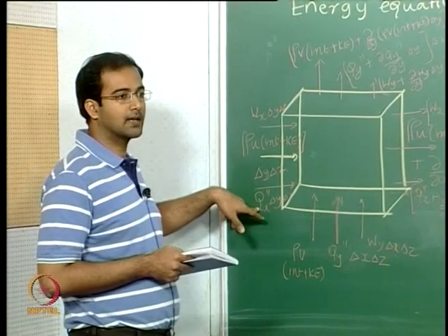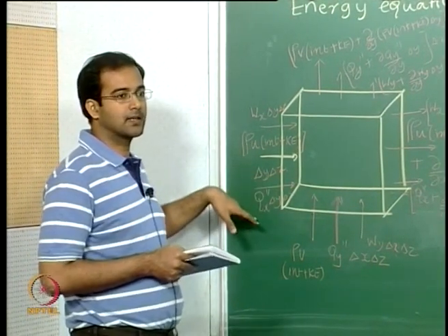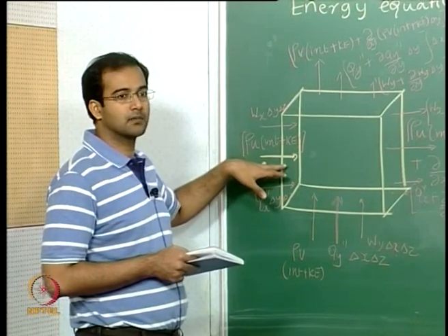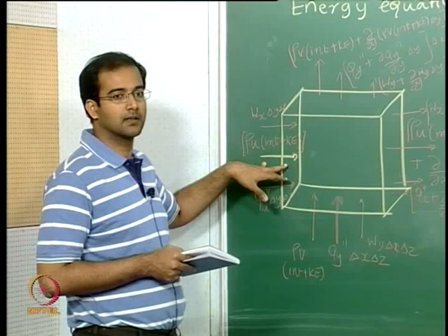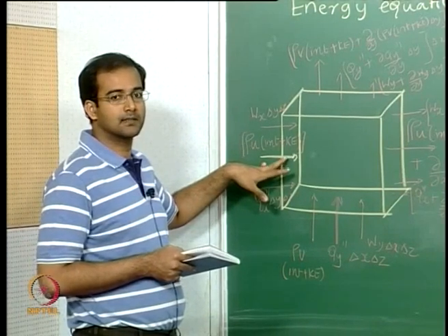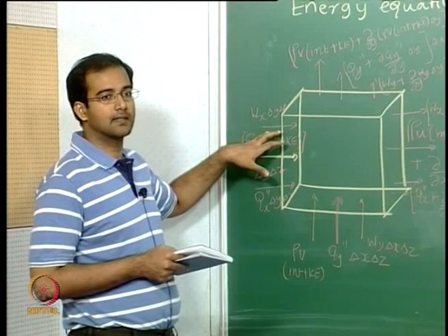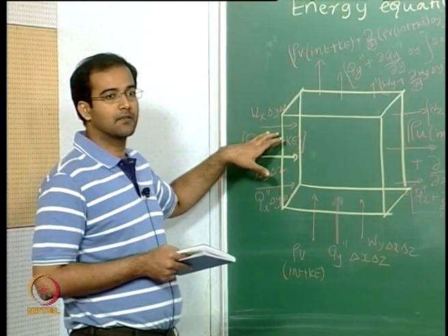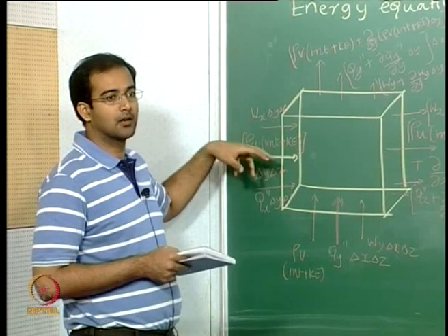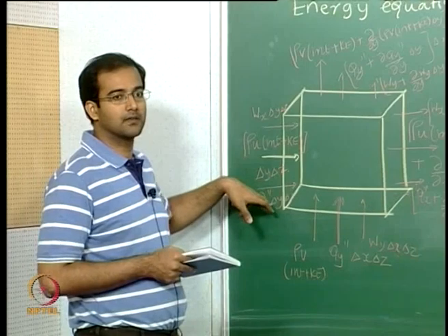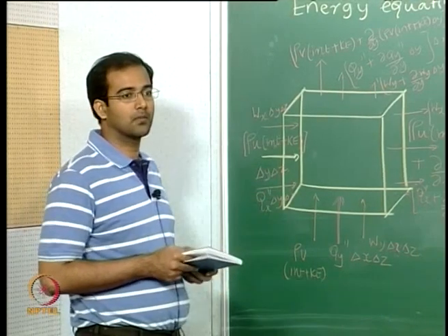So you have heat conduction, which is essentially transferring the heat by a diffusion process, and you have energy transfer by means of efflux of the internal and the kinetic energies, and also you have work transfer. So all the three are simultaneously effluxes or fluxes of contributions of internal and kinetic energies, the work, and the heat, which are all acting on the control volume boundaries.